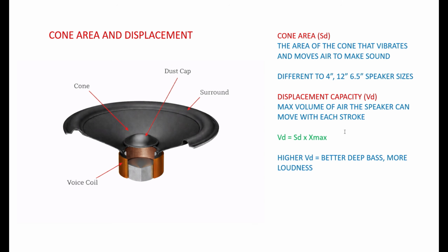So why is this an important spec? The answer is that the higher the VD value, or displacement capacity value, the deeper the bass and the more volume it will make. And this is especially important when you're comparing subwoofers or mid-bass speakers.